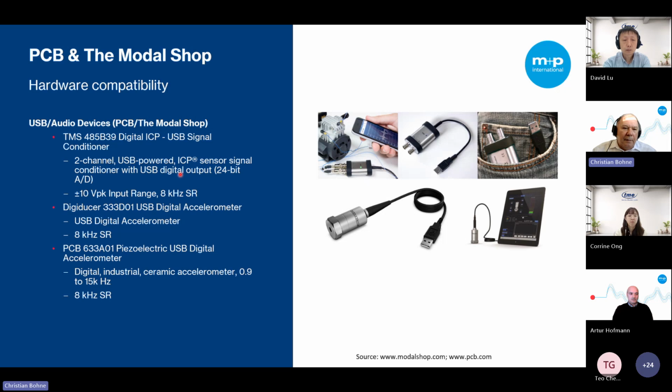Yeah, so we supply a constant current to these ICP sensors with a computer, not with the data acquisition unit. And for simple application, this might be the right choice.